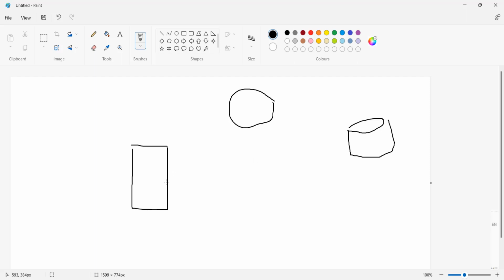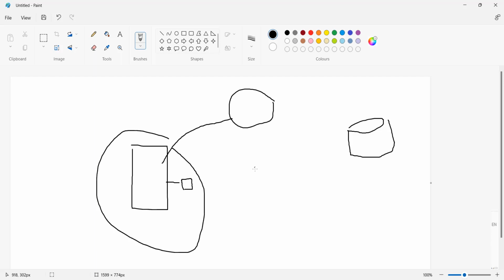So for example, this ESP8266 is connected to a temperature sensor. So the data collected from the sensor, such as temperature and humidity, are then required to be transferred to a database, stored to a database. So to be able to do that, this microcontroller will be required to connect to the internet through a Wi-Fi access point.